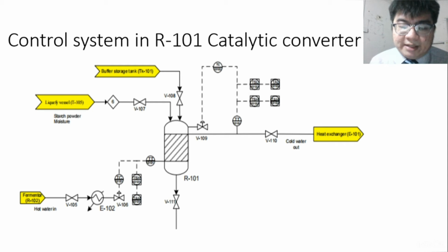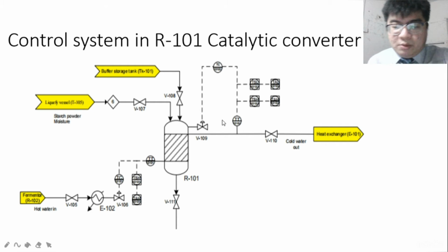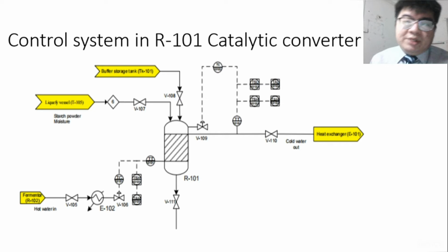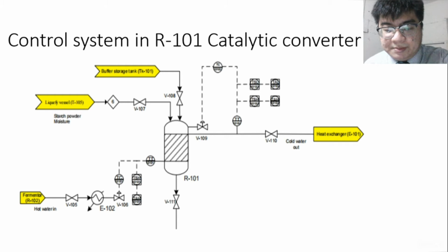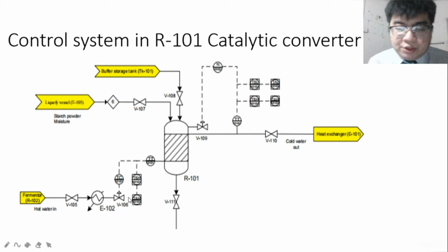before entering the tanks. It is also equipped with temperature alarms on both sides, which are the temperature high alarm and temperature low alarm. Both temperature alarms will trigger if the temperature is too high or too low from the normal situations. There is also a switch connected to the alarm. This one, TSH.